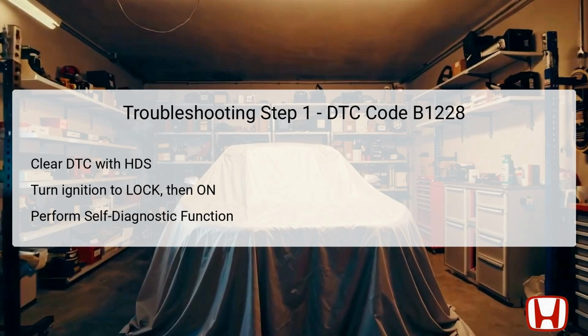Begin troubleshooting DTC B1228 by first clearing the fault code using the HDS, or Honda Diagnostic System. This action removes any stored codes, allowing you to verify if the issue persists. Following this, turn the ignition switch to the lock 0 position and then to the on 2 position. This helps reset the vehicle's electronic systems.